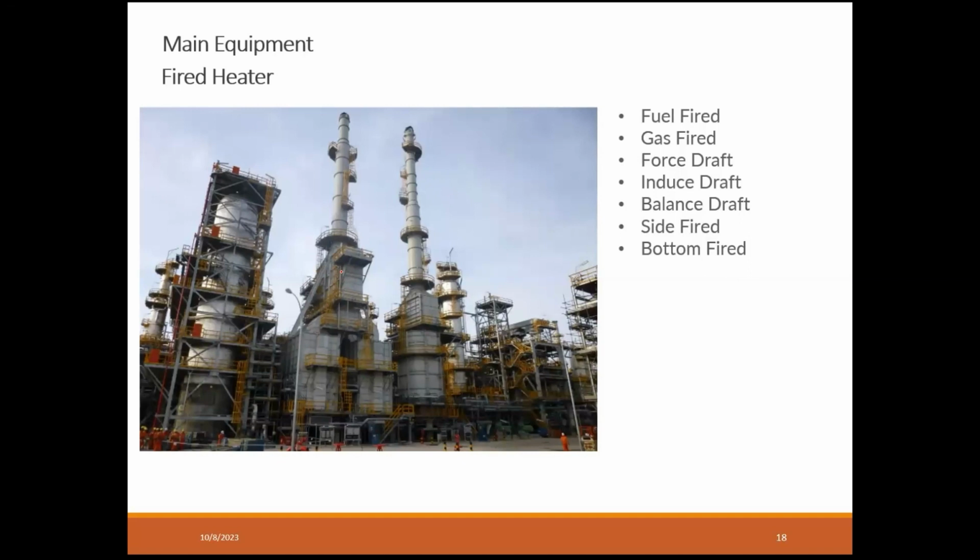If this is the boiler, meaning this is a waste heat boiler. But the boiler that I mentioned in the cogeneration plant is basically a main burner, a very big burner that will be used to fire up the natural gas. Then it will pass through a heat exchanger.